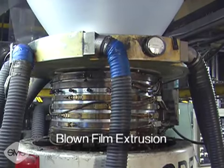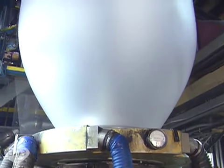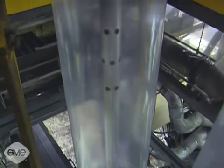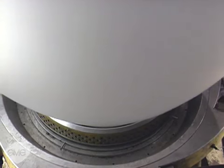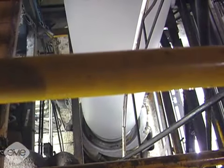The blown film extrusion process uses an extruder to pump molten plastic vertically up through a die having a 360-degree annular opening on its top. This produces a tubular film extrusion, which is subsequently filled with air. As a result, the tube expands out into a bubble, having a diameter larger than the diameter of the annular opening of the die. The tubular bubble cools as it is pulled up.